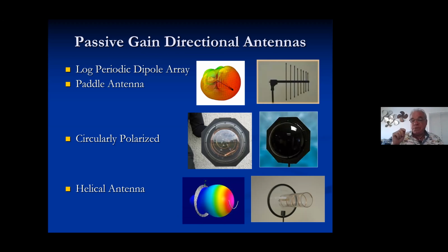For example, on a typical show, let's say you had 6 or 8 in-ear monitors and a RAD combiner, which you can kick up to 1/4 watt on each signal. Well, that's 2 watts of radiated power now. You put that next to your wireless microphone receivers that are looking for these minuscule microvolts of RF energy, and that 2 watts radiated is going to splatter onto your mics and create interference. All you have to do to get your mics to work is turn your in-ear switches down to 50 milliwatts, and that covers the stage just fine. So in other words, more is not better. What really is needed is just enough to get it right.